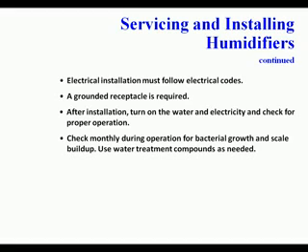Check monthly during operation for bacterial growth and scale buildup. Use water treatment compounds as needed, and be careful in their use. Some people are allergic. Always follow the manufacturer's directions and check out the manufacturer's technical specs before installing a humidifier.